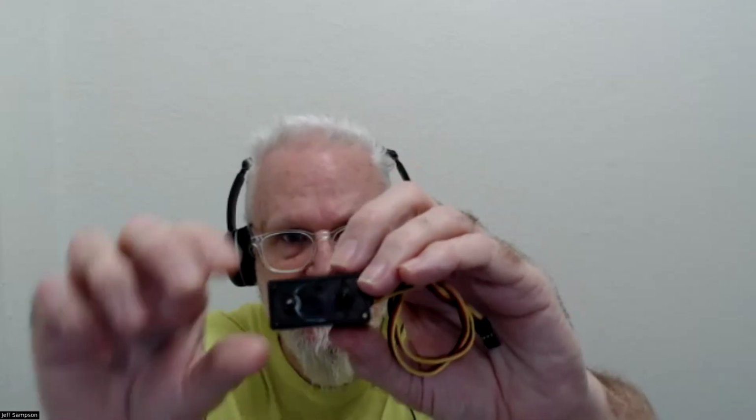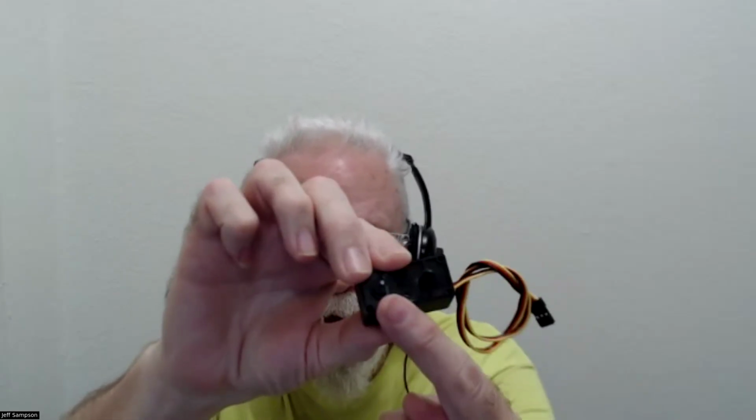Another thing I was thinking about: if you go in there, that pot is just soldered on the board. You could cut the wire between the pot and the board, and then run three wires, power, ground, and the signal, out and put a pot right on your big motor, and then hook them up to this thing. And then basically you've created a giant RC servo. So it should be able to do positioning at that point.